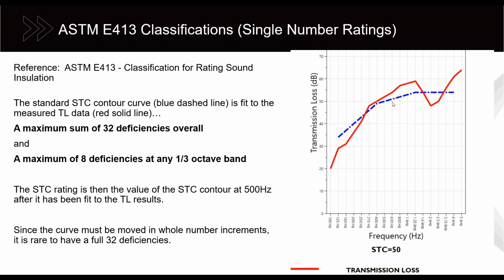Then the STC rating is the value of that curve at 500 hertz after it has been fit. So you see here, you have STC 50. One thing to note with STC ratings is there is a very wide range of wall performance contours that could all fit to the same STC rating.